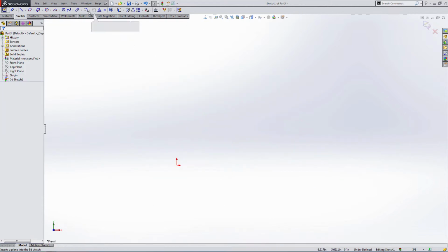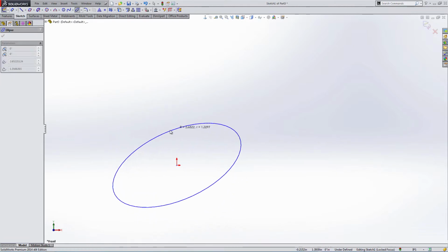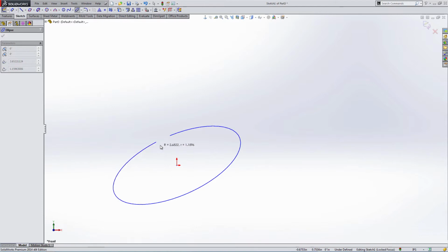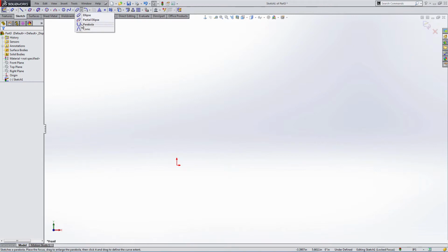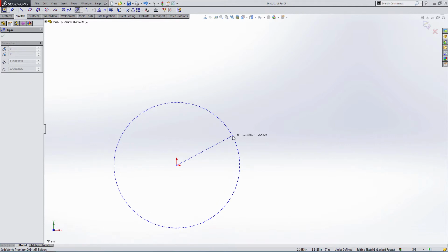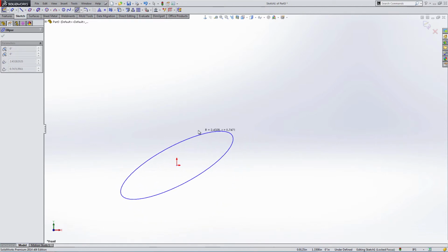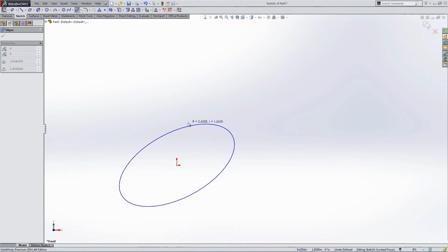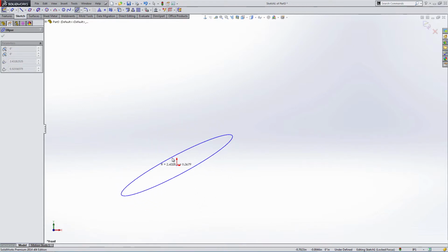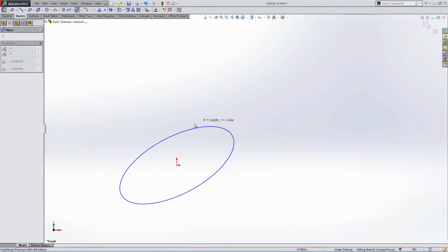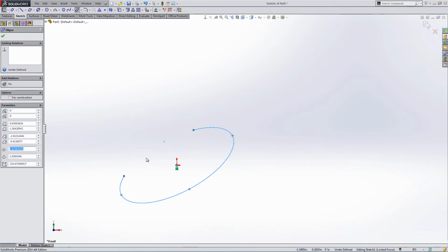Then you've got a partial ellipse, and that would be this one. So similar set of commands, first direction, second direction, and then arc. And it also sets the first pick point, which I don't love, but that's the way it works. So pick number 1 is your center point, pick number 2 is your first direction and the diameter in that direction. Pick number 3 is the second distance, second direction, and where you pick on this ellipse is where it's going to start. So if I want it to start here, that's where it's going to generate from. Partial ellipse.